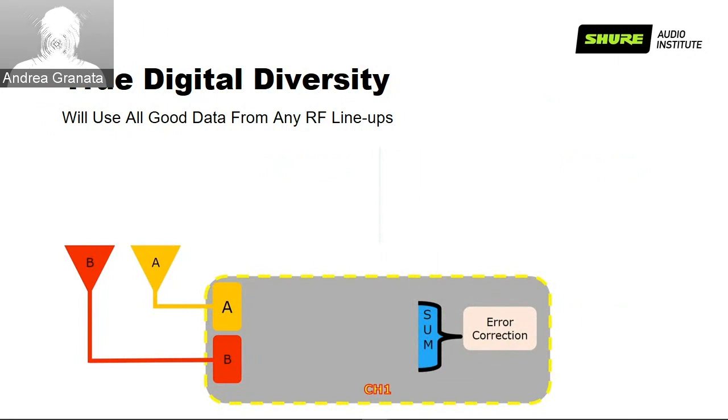The receiver will read this pattern of bits and will be capable of better understanding the signal-to-noise ratio, the carrier-to-noise ratio at RF level. So if out of 32 bits of this print mark I receive only 8, my transmission is very much disturbed. If I receive 32 out of 32, it means I'm working in ideal conditions. Everything is very good.